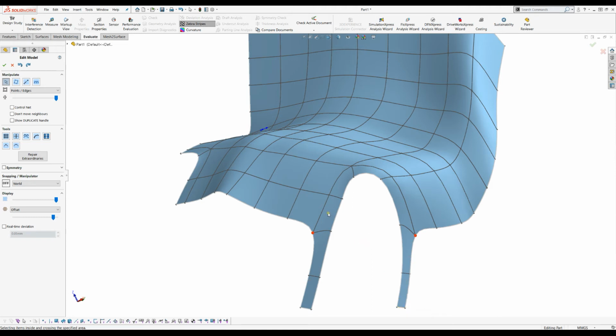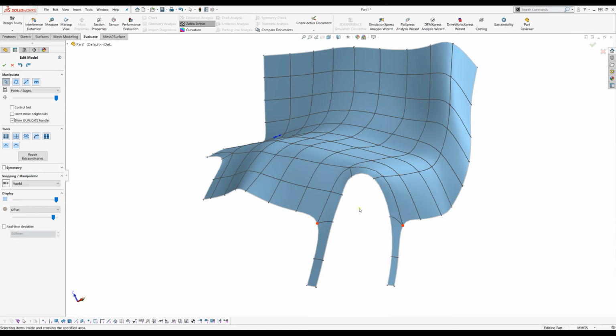So now when I want to close, one way is I can just duplicate my edge here. Let's duplicate this and start closing this one with this one. But in some cases it's a bit tedious and it takes a lot of time. So what we have here with the control, I can select what you see, 3 edges. And if I have another chain with another 3 edges, we can use the bridge edges command.